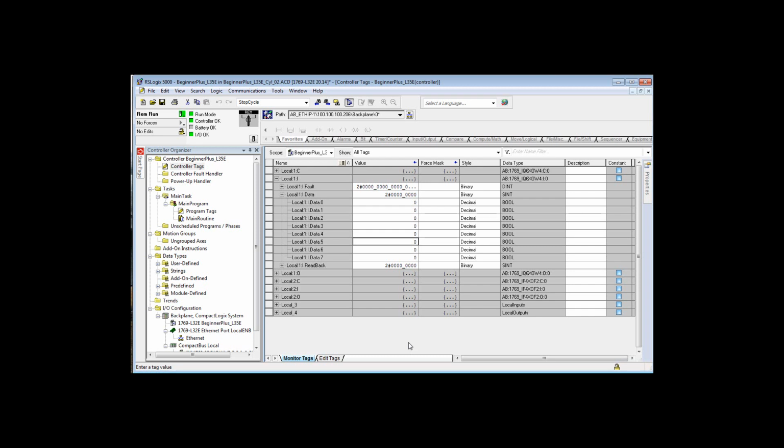It may have actually gotten into memory, and it may have actually changed that memory location for about 100 or so microseconds. But because you're updating the state of those bits from the real input modules 5-6 times every thousandth of a second, you might as well say it just didn't change.